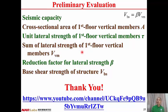of the first floor vertical members, VVM. Because not all the vertical members develop their strength at the same time, there's a reduction factor for the lateral strength, beta. From beta and VVM, then we can have the base shear strength of the structure, VBS equal to beta times VVM. That's the seismic capacity of the building.